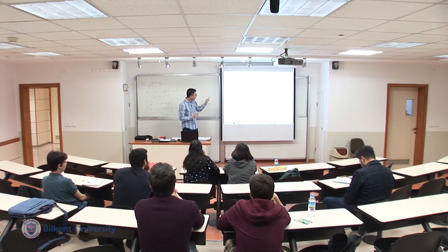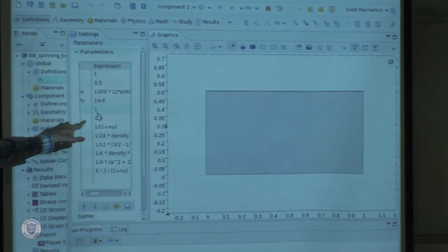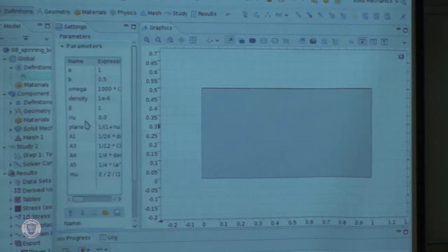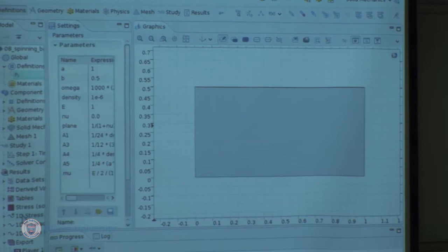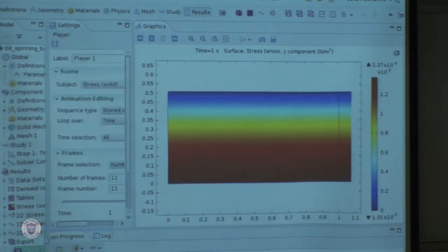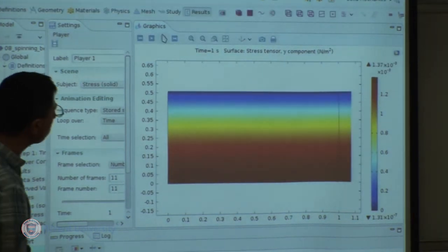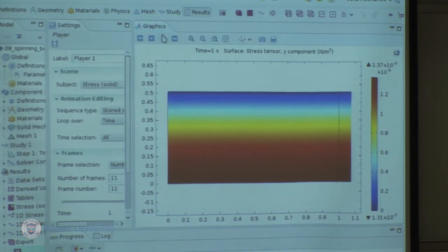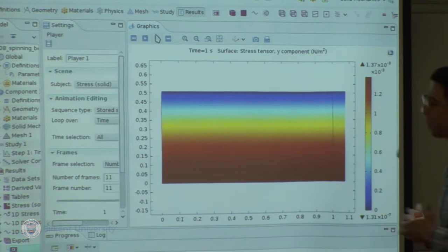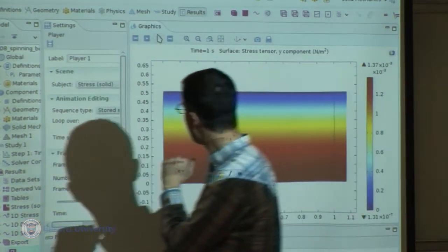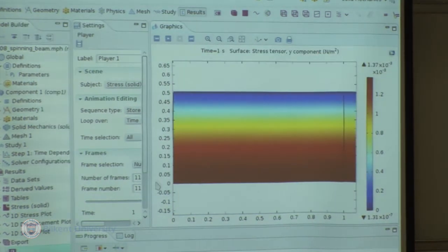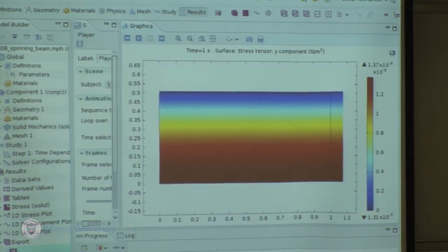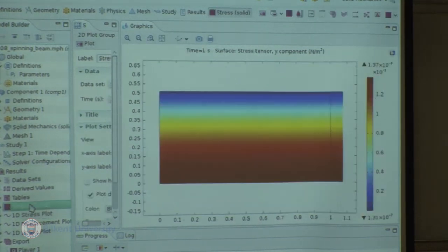Anyway, so now finally, let me first begin with a Poisson ratio of 0. So I have the parameter here, and I'm going to vary that. All the other parameters are just entered magnitude-wise without the units. So let's now go ahead. If there is no Poisson ratio, of course, I pull, and there is a very symmetric deformation. The rectangle remains a rectangle. And what you see here is the sigma 22 component of the stress. So let us make this thinner. Oops, sorry. So this is sigma 22.